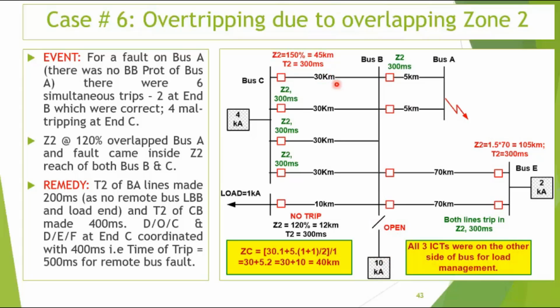Normally, every time this doesn't happen. But on that particular day, this was open, this fault level was not available to multiply this impedance so that these relays do not see this fault in zone. This is one case study I have seen.